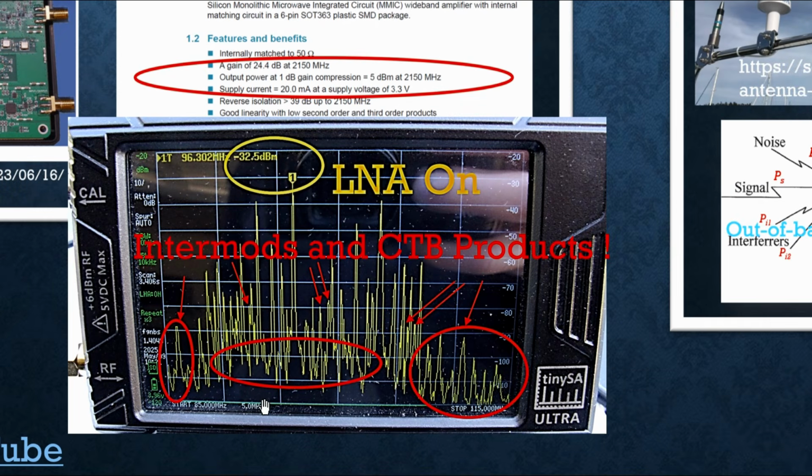The sweep is going from 85 megahertz up to 115 megahertz. There should be no signal right here. This is actually caused by mixing of some of these stronger signals. Likewise, at the top end, up to 115 megahertz, yeah, there might be some aircraft signals, but these are not them. And in episode 4, we discussed how you can figure out if these are real or not. Basically, you turn on an attenuator, and if they drop a lot, then they are intermods.